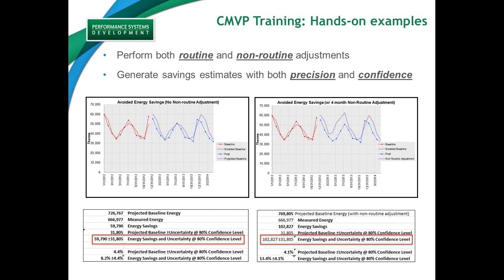Both the charts look very similar to the chart we saw 5 or 6 slides ago, which was, again, IPMVP Equation 1. In each of these charts, you see on the left the pre-retrofit or the baseline energy period. That's the red dots, the red dotted line. The red line without the dots is the model baseline, so that again represents some sort of mathematical relationship that has been created to represent the baseline period.